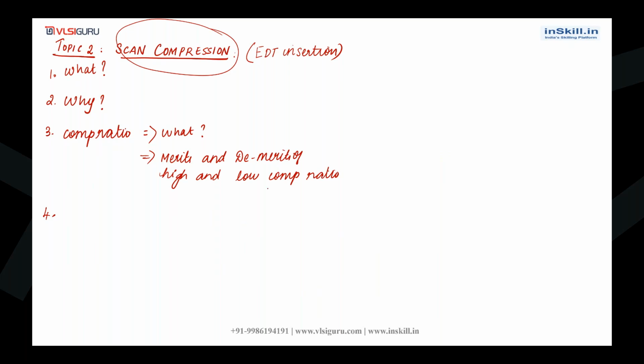we will be adding up a logic called EDT logic. The full form of EDT is embedded deterministic test, which is nothing but the EDT logic. So if you want to achieve scan compression using Mentor Graphics tools, you will be adding up a logic called EDT, embedded deterministic test.